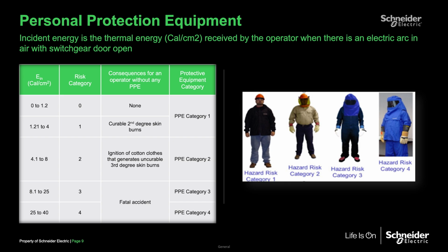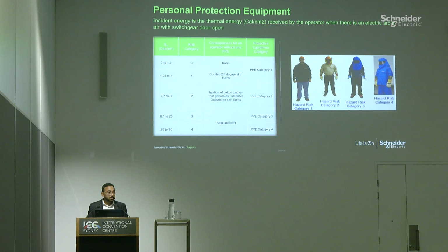For consultants, for engineers who are driving specifications, this is something which has been asked multiple times by many consultants. So we are saying level 1 PPE, go for it. These are the levels of PPE, but don't stop here because you will not be able to take the heat, or really the hit, of arc flash just by deploying a PPE kit.